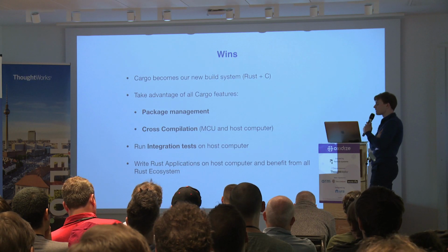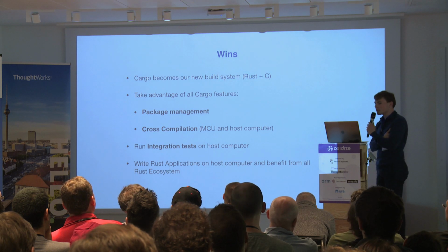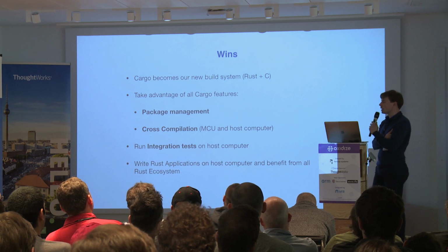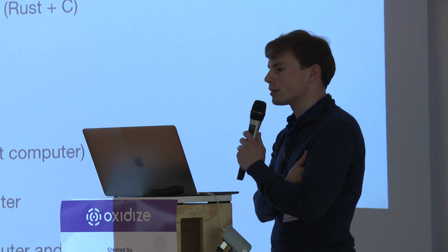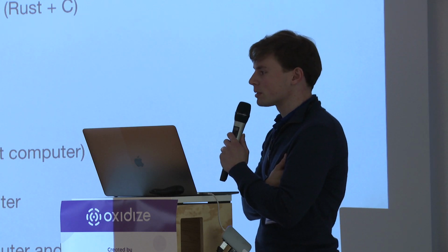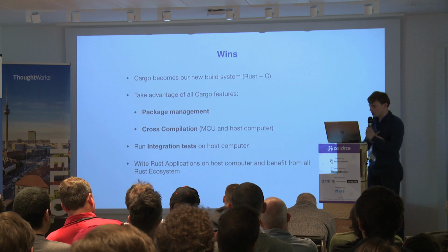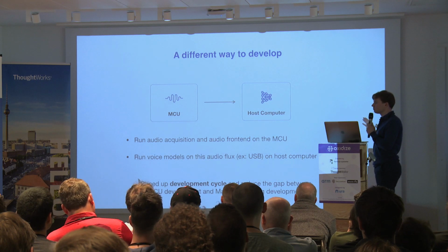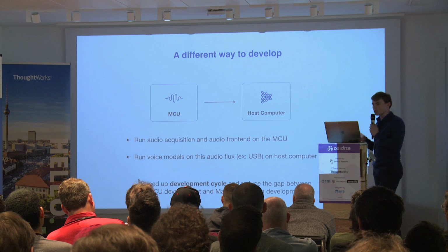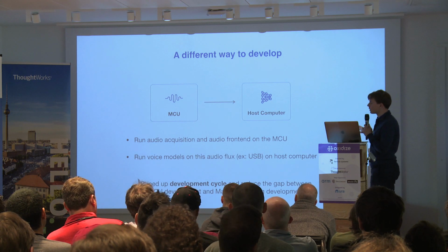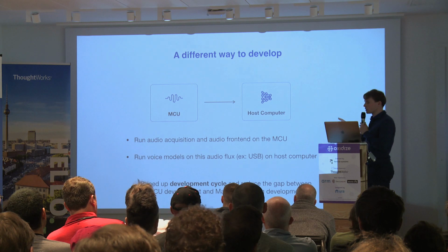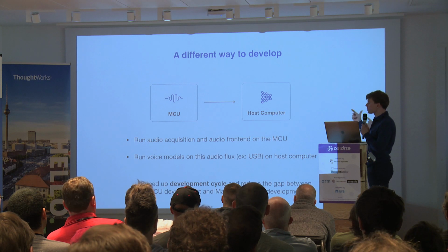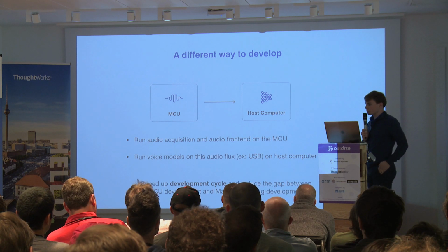And the final point, as I said, is that you can start to take the whole ecosystem to build Rust applications that will work on your computer. And sometimes, I will explain later, you can do MCU development, but by writing on the host computer. Because what this brings is a new way to develop our system. Instead of developing everything for the MCU and deploying on the MCU, we will run only the audio acquisition, the audio front end to clean the signal, and then we output everything on your USB port, and the whole solution will run on the host computer.